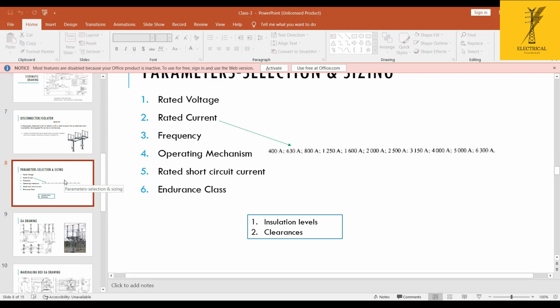My isolator should be capable of electrodynamic withstand and also thermal withstand capabilities. We also talk about the tubes, the material for the tubes, coating, and type tests, everything in depth in the technical specification.